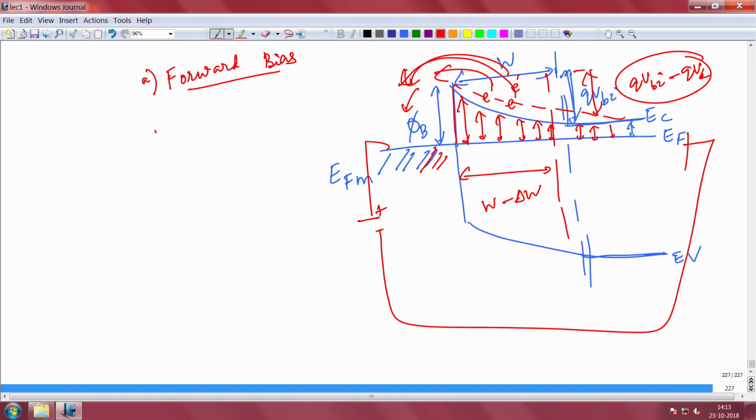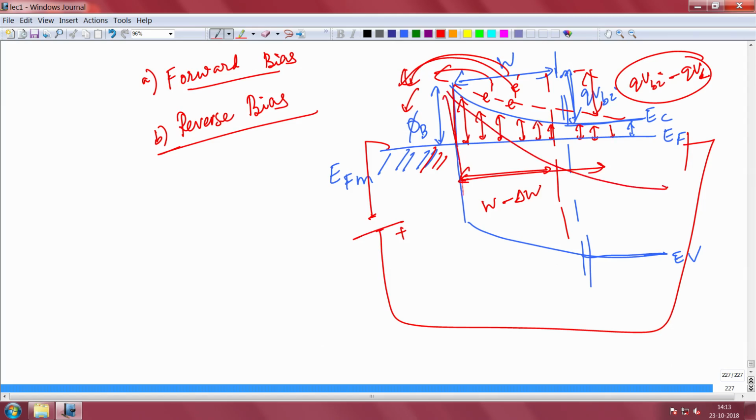Okay. Similarly, when you have the reverse bias junction, you are going to apply a negative bias on the metal with respect to the semiconductor. You are going to make the depletion width longer and the barrier even larger, like this. Okay, the barrier will be larger and electrons will be pushed from metal to the semiconductor side, but this barrier height is there, which is not going to change with bias. So you will have very little current, very low leakage current, until it breaks down, right.